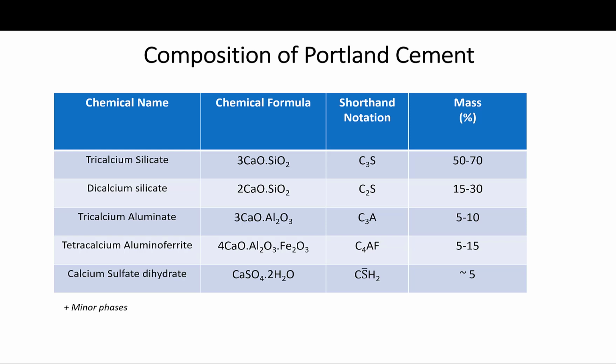So let's see how every phase contributes. Let's first reiterate a couple of points. The cement reaction with water is an exothermic reaction, meaning it gives off heat. The reaction of calcium silicate phases with water is what produces the calcium silicate hydrate gel, which is responsible for the strength. These two phases, C₃S and C₂S.